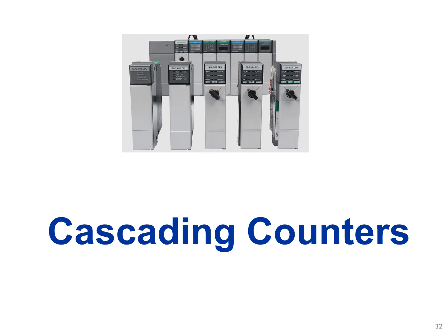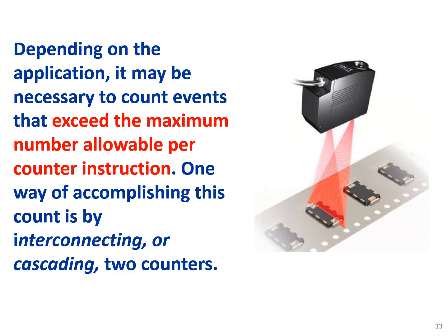Cascading counters. Depending on the application, it may be necessary to count events that exceed the maximum number allowable per counter instruction. One way of accumulating this count is by interconnecting or cascading two counters.